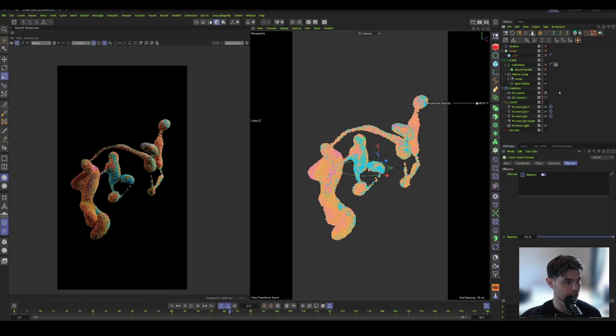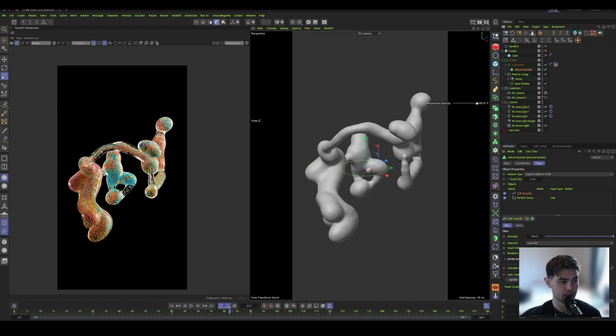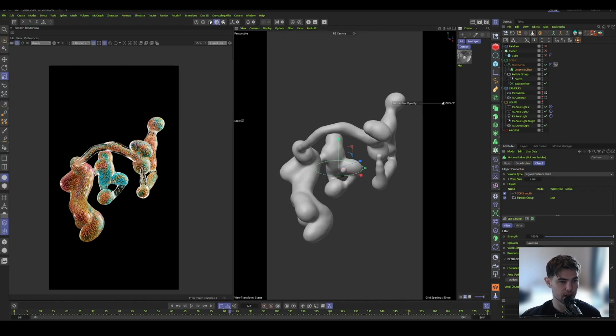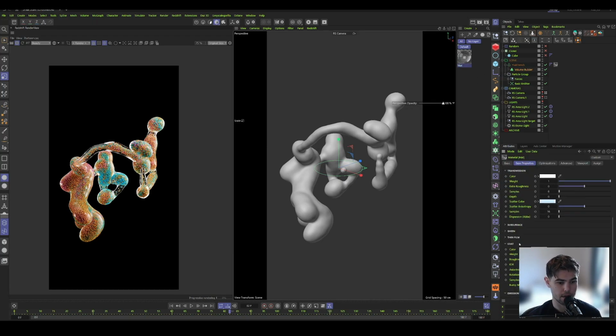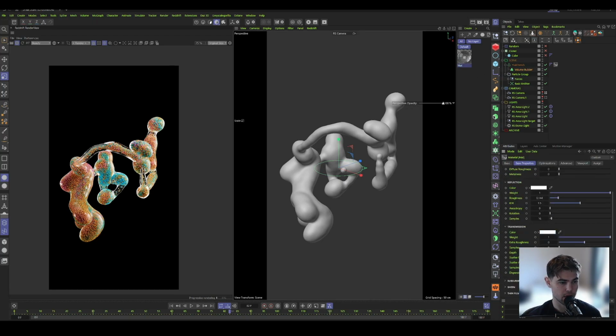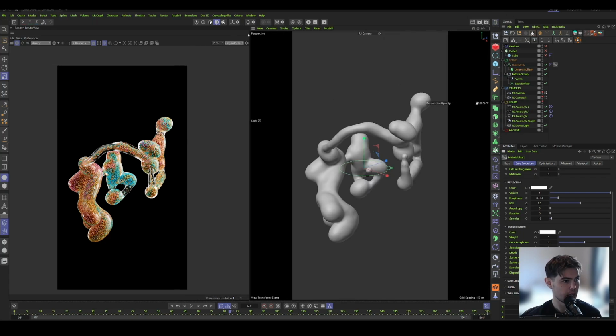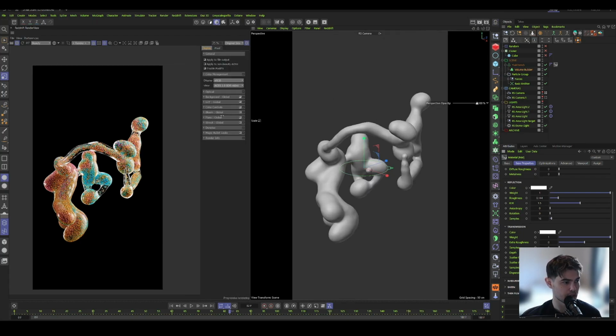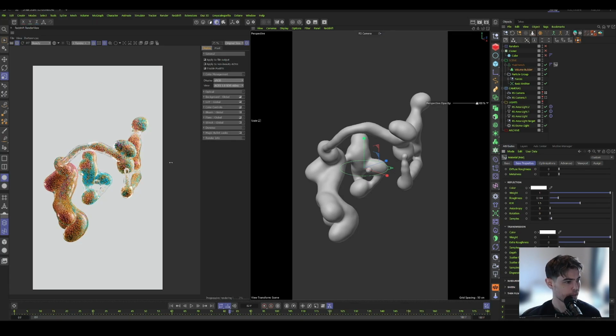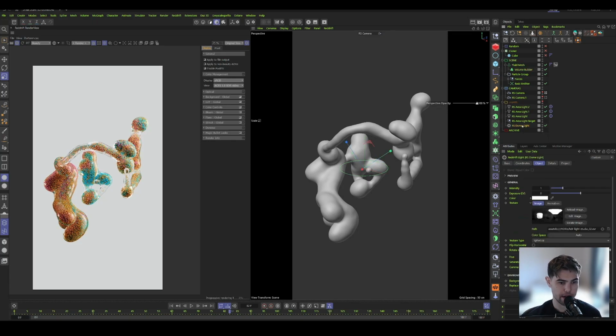But let's get back our particles, and then let's turn on our fluid mesh. So literally for the particles, I didn't have a material. In this one, I just had one transmission material with a lower roughness value. And then I used the background in the post effects and have a dome light that is, I think, in the asset browser, and then a couple area lights as well that are just targeted towards the center. So that is pretty much everything about this one.